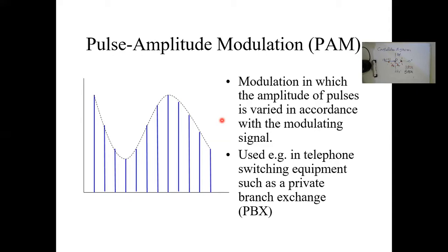You just send this stream of pulses. The amplitude of these pulses indicates the message. So in the receiver, you are going to track these amplitudes in order to reconstruct it. It seems like you only did the sampling process and you did not do any quantization or encoding process. It's one step toward digitalization. And you send the message directly to the receiver using your dedicated channel.